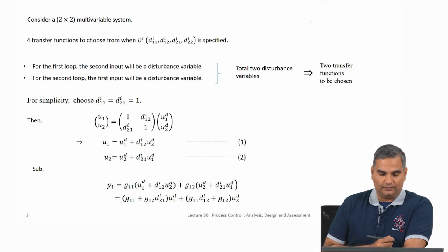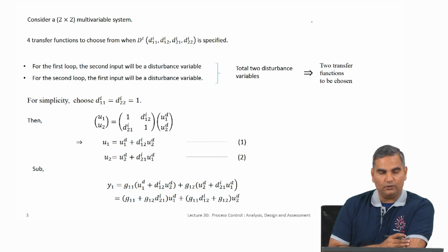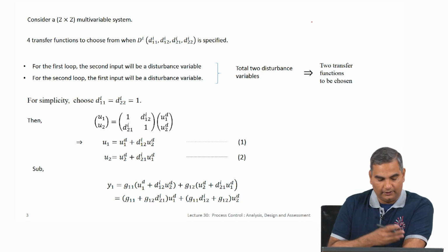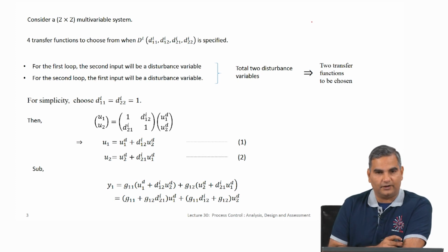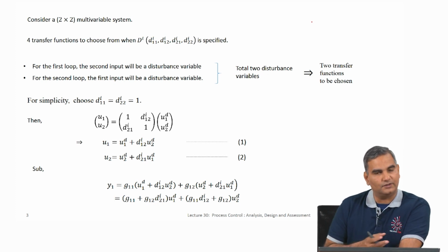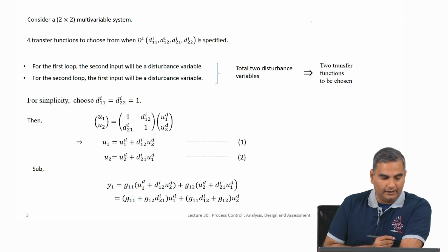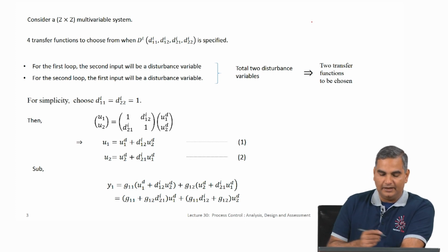Ultimately the true manipulated variables are u1 and u2. You might say, okay, I am computing u1 decoupled, u2 decoupled and so on. You could go ahead and compute that, but even then you still need to figure out what u1 and u2 actually are in the controller implementation situation. Okay, because those are the physical manipulated variables. So, supposing I have come up with some u1 decoupled and u2 decoupled, which I will show you how we come up with, then I might say, if I am going to recalculate u1 and u2 from these, I could come up with some linear transformation.